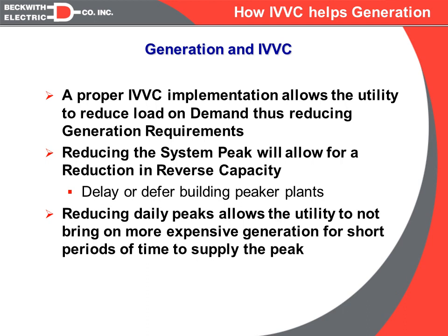required. So if a utility is reaching the maximum limits of the existing reserve capacity, then they would have to look at constructing another power plant, typically a peaker plant, to be able to support that additional reserve capacity required for the new peak. The other way we can do it is on a daily basis by reducing the peak